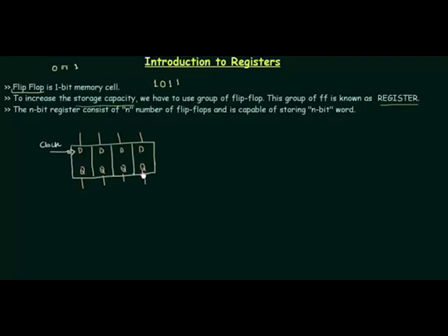In a sequential circuit, the clock pulse is not generated individually for every operation, but it is generated and given to all the operations. By this I mean, I'm not going to generate the clock for this flip-flop, then this flip-flop, then this, and then this. I'm not going to generate 4 different clocks for these flip-flops, but I will have the same clock and it is given to the different operations.